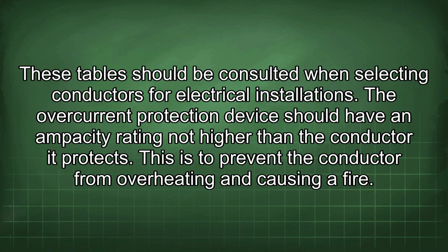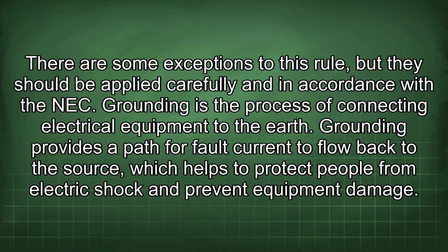The overcurrent protection device should have an ampacity rating not higher than the conductor it protects. This is to prevent the conductor from overheating and causing a fire. There are some exceptions to this rule, but they should be applied carefully and in accordance with the NEC.